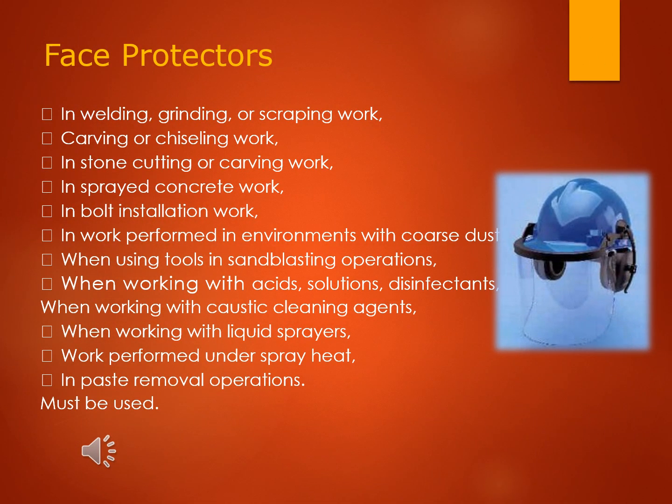Face protectors must be used in welding, grinding, scraping work, carving or chiseling work, in stone cutting or carving work, in sprayed concrete work, in bolt installation work, in work performed in environments with coarse dust, when using tools in sandblasting operations, when working with acids, solutions, disinfectants, or caustic cleaning agents, when working with liquid sprayers, work performed under spray heat, and in paste removal operations.